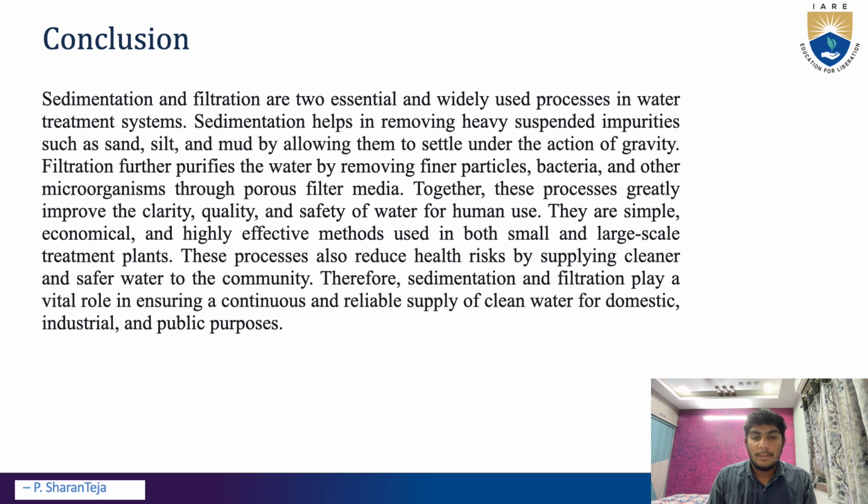Conclusion. To conclude, sedimentation and filtration are two essential methods for water treatment. Sedimentation removes heavy suspended impurities by gravity. Filtration removes fine particles like microorganisms through porous material. Together, they improve water quality and safety. They are economical and reliable and widely used across the world.